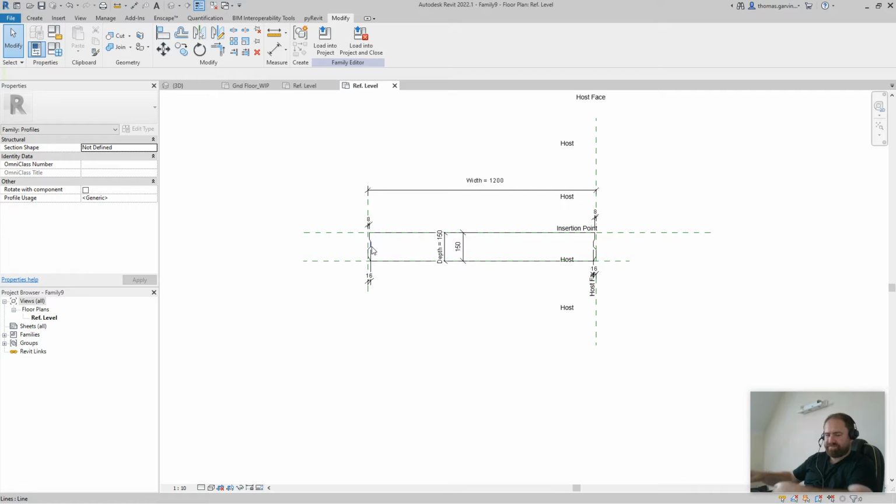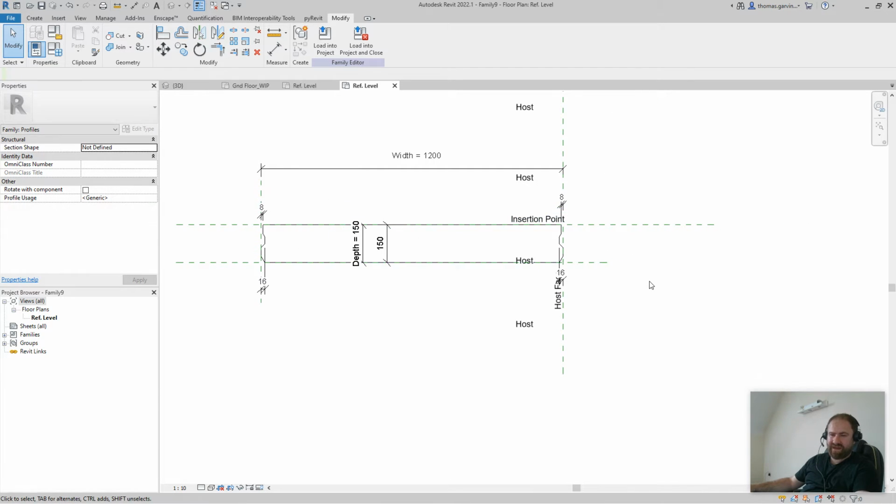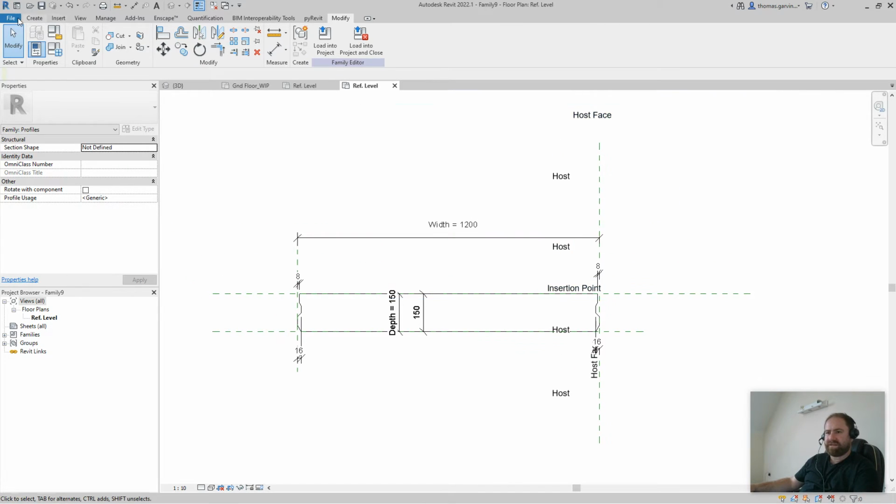Okay, now you might be inclined to put the openings, the little holes in here in this profile, and the only way that you can do that to make it parametric is to put an array on it, so that you get more or less them depending on the width. And it should work, but it doesn't. Okay, so that's not going to work if you put this into this profile. Now you can go ahead and pause this and try it yourself, and then you'll find out it doesn't work, and then you can come back. Okay, so I'll save this guy.